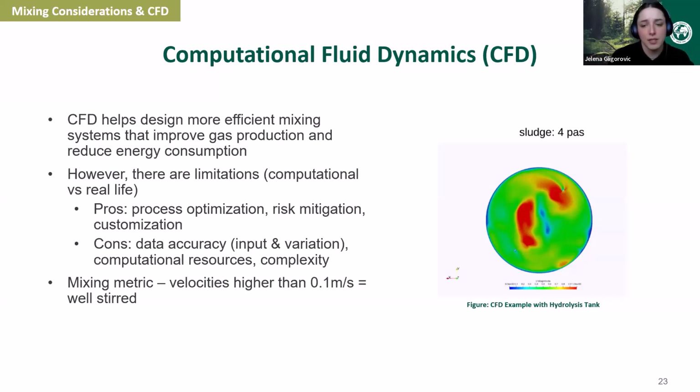There are limitations to CFD, mainly the differences between what you get on a computational basis versus what you get in real life. So again, garbage in equals garbage out. If you don't know what your feedstock is, what the viscosity is, what the variations in your feedstock could look like, it reduces the accuracy of your CFD analysis.